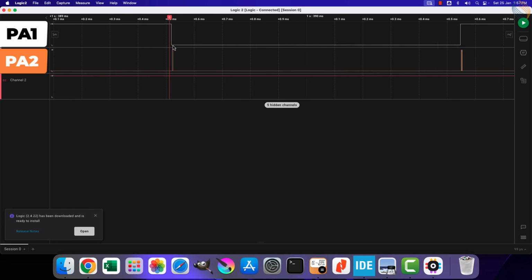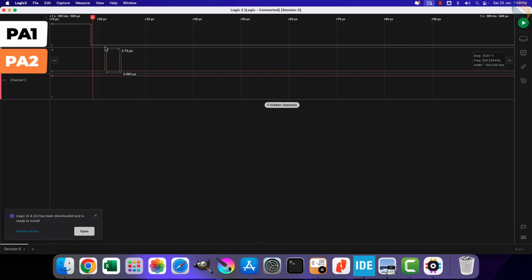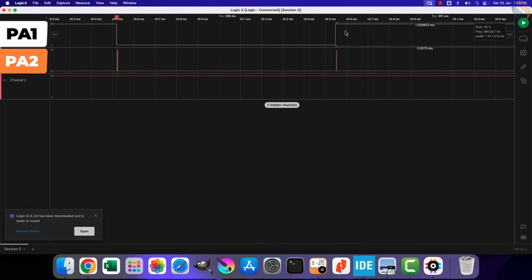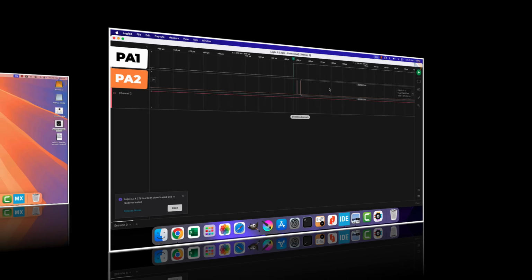The injected channels are converted after the regular channels. If there are a total of 16 regular channels and 4 injected channels, using the auto-injection mode we can convert a total of 20 channels. If the continuous conversion mode is enabled, these 20 channels will convert continuously.